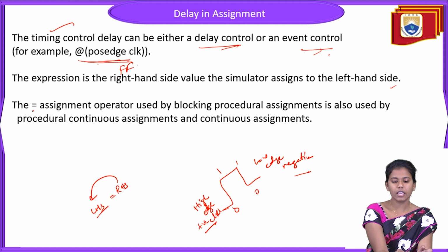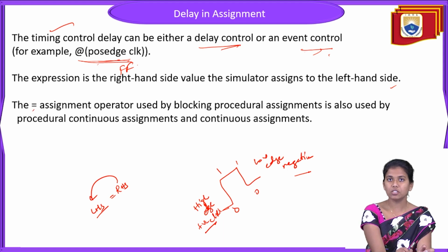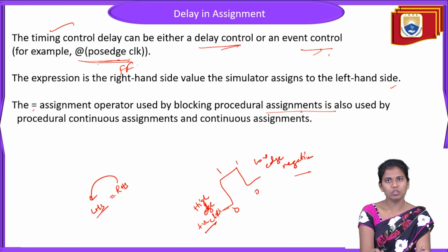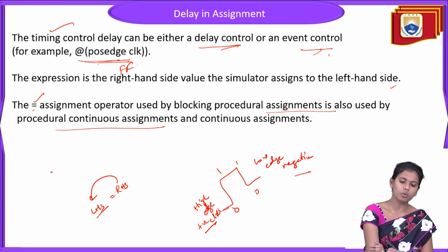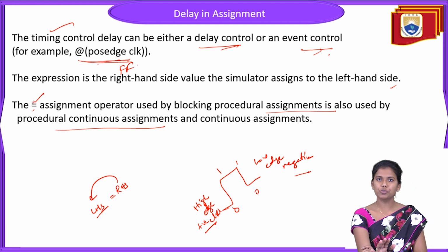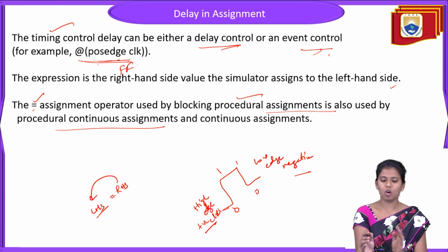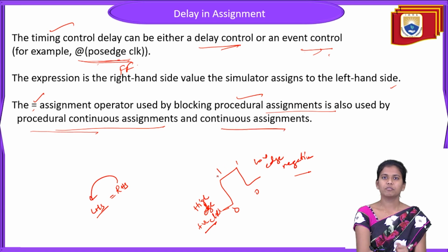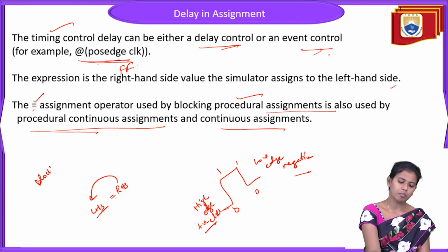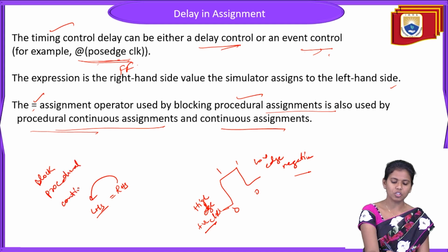That means the equals-to assignment operator is used for blocking procedural assignments, continuous assignment statements, and also for procedural continuous assignment statements.